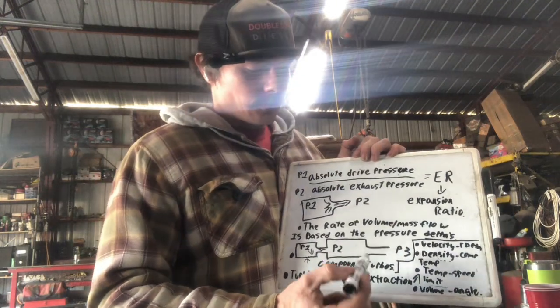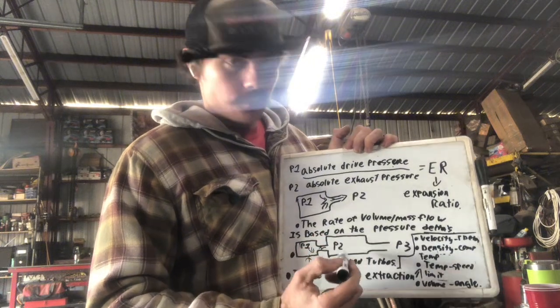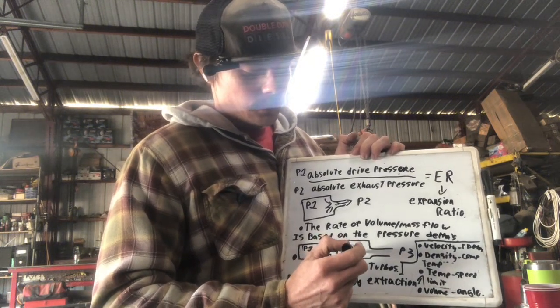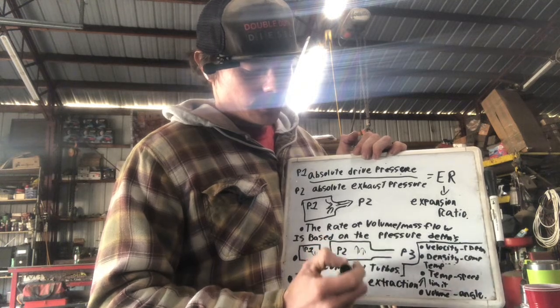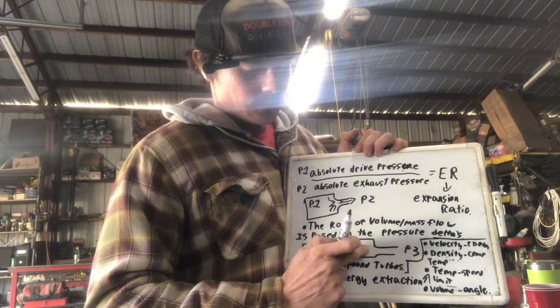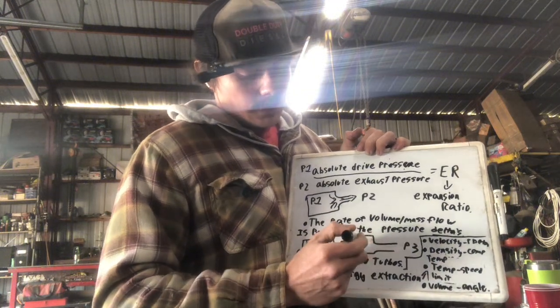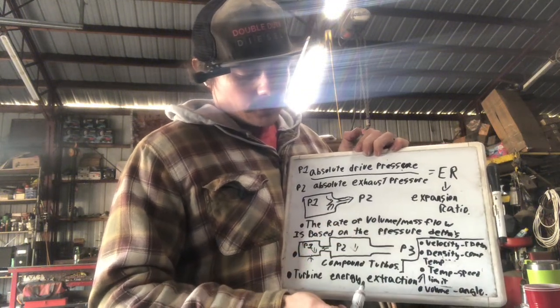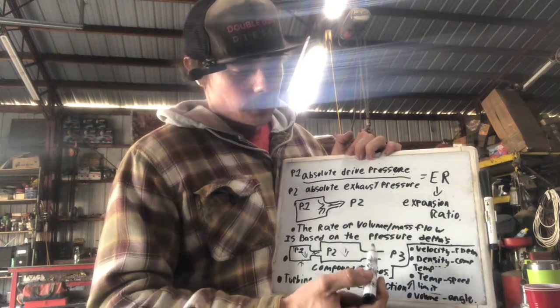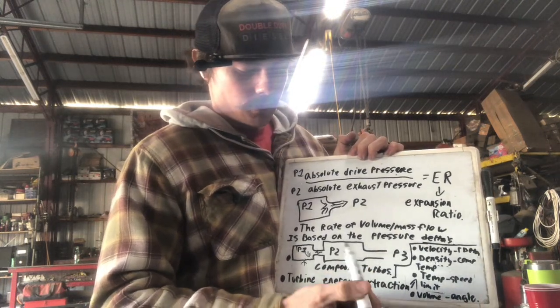So on a lot of setups, what I've been doing is taking P2's interstage drive pressure and putting a bigger turbine housing on it or a bigger turbine wheel in it. What's that do? It'll lower interstage drive, because the bigger the turbine housing or the bigger the turbine wheel, the more mass and volume you can move through per moment of time.